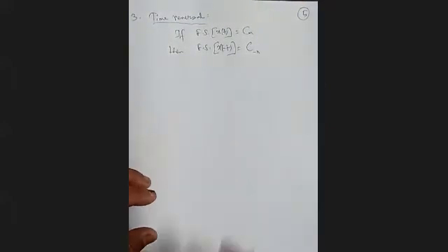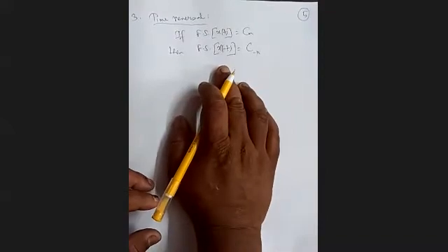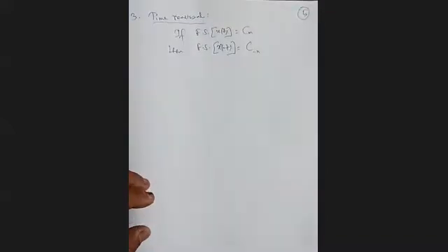So when it is flipped in time, it will be flipped in frequency also. So all the negative frequency components will become positive frequency components, and positive frequency components will become negative frequency components.